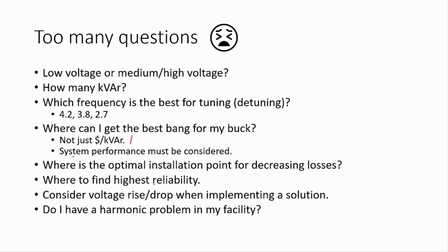Now, reliability is always to be considered as well, because if you install 100 capacitors in every machine in your facility, it's bound that one of them will fail, and then another and another and another. But if you install just one big capacitor at the utility connection, it's very likely less to fail. So there are many sides to this problem, as you can see.